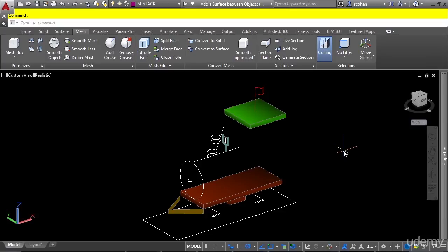Now, the letters M and N are used to reduce the confusion with the standard X and Y axes. However, it's generally considered to coincide with those axes. So in other words, the X-axis direction is where you control the surf tab 1 variable, and the Y-axis direction is where you control the surf tab 2 variable, and the meshes that will get generated. So let's look at what the surf tab 1 variable is set to. It's set to 6. Respectively, surf tab 2 is also set to 6. Now let's look at these commands with this variable set to 6.